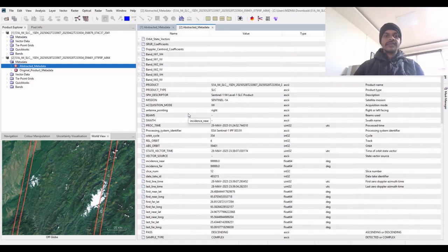So first we will discuss why we are taking the SLC image, single look complex images, and why not GRD. When it comes to landslides, they are not just a sudden event. In many cases the ground starts moving very slowly, sometimes just a few millimeters or centimeters per year, before there is a failure. To detect this slow movement, we use SAR interferometry, or we can call it InSAR, which measures ground deformation using phase information from the radar signals. So the key requirement here is the phase.